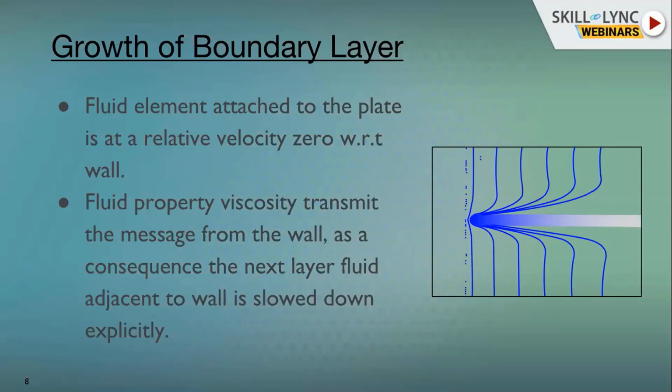The flow we can assume inviscid when it is far away from the solid surface, right? The viscous property of the fluid is restricted near the solid surface. Even after 120 years of the discovery, the boundary layer phenomenon has great relevance for analyzing a lot of day-to-day flows and their applications.